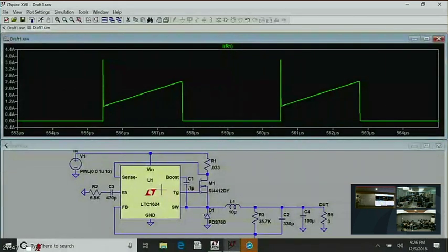So when one of these clock pulses comes in, it sets the flop and grounds the output of the current sense amp. Okay, and the time it's shorted to ground depends on the width of this pulse. Then you unblank this thing, and then you can monitor the inductor current. This width here, depending on which controller you're using, might just be 100 nanoseconds. So to scale here, it would unblank the thing at this point. And that means you could quickly blank this thing and then monitor the current with a huge bandwidth, many megahertz of bandwidth, to reset the flop at the right point.